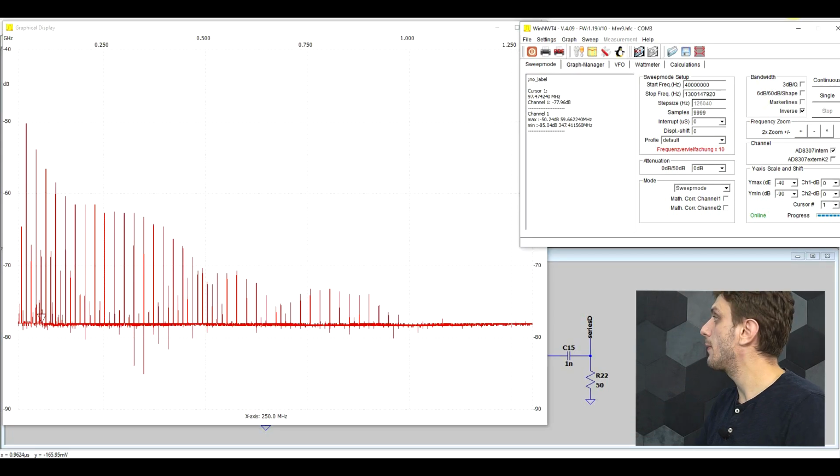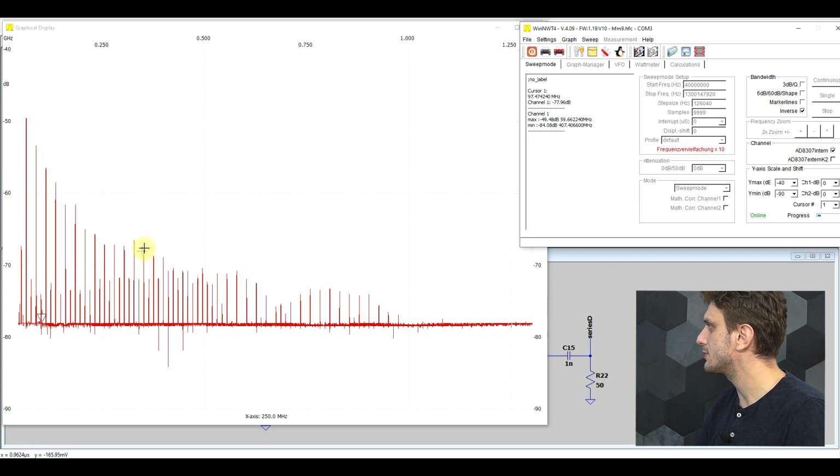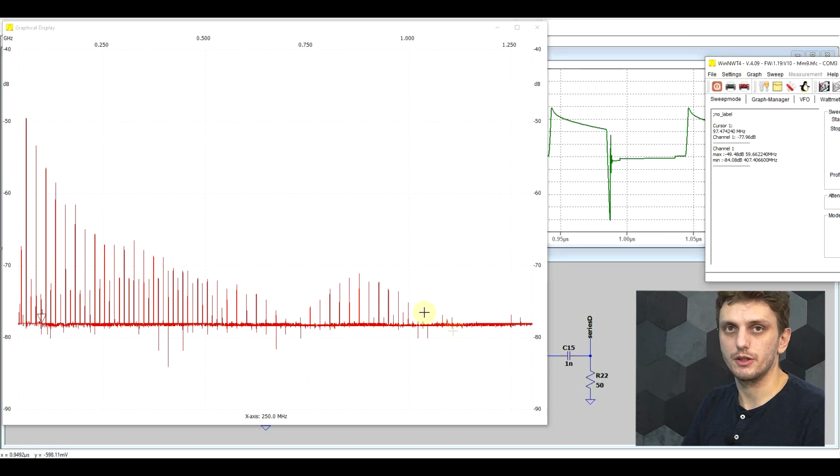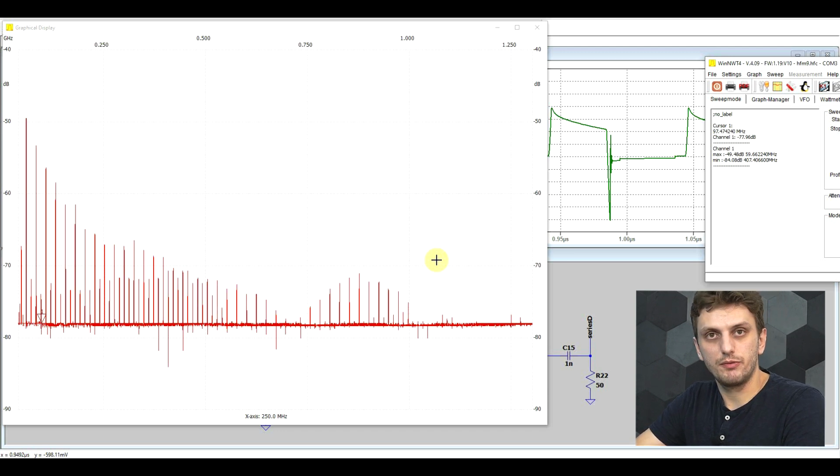And by adding this thing, if we rerun the measurement, we see again some of the spikes changing, also from lower frequencies. But we also see the spectrum slowly changing, so we see some spikes going on even later, so above 1 GHz. Now of course some of the spikes are below the measurement threshold of the spectrum analyzer, but if I would have an extra amplifier added, then we would see much more clearly the effect of these diodes added as step recovery components. So all in all, a proper comb generator is a far more complex circuit than this.